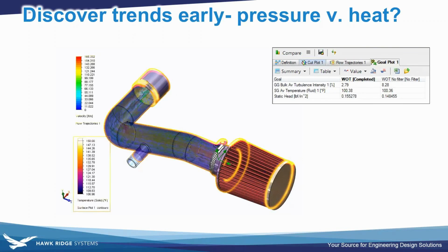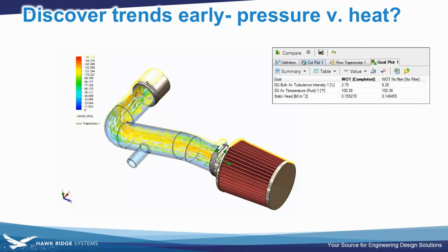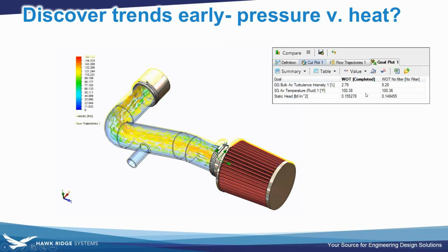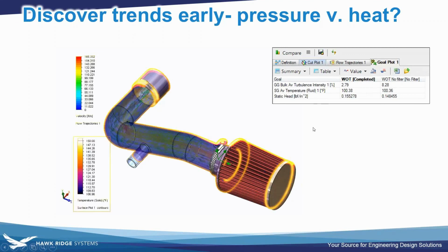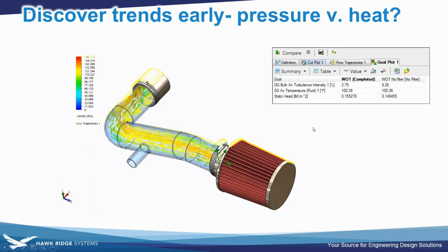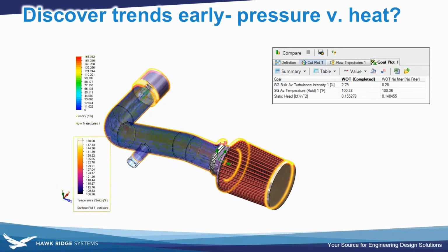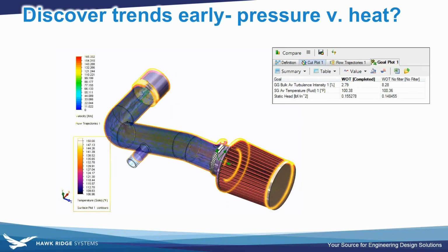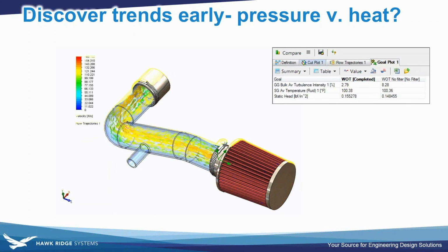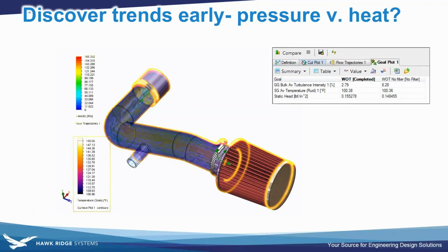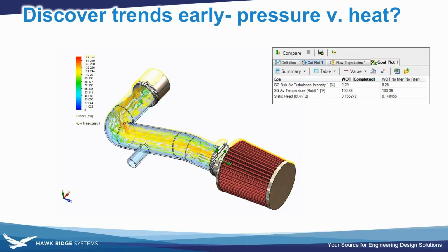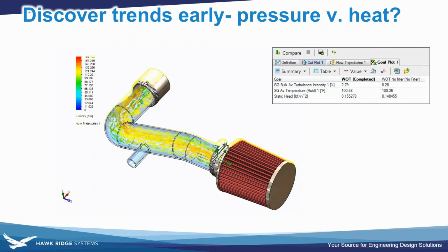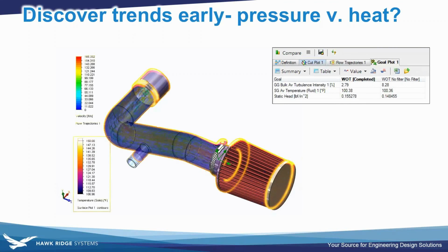And that temperature was only 100.3 or so degrees. We assumed that the air coming in was 100. So that means there was minimal temperature rise of the air going through the ram intake. So that means that this airflow was sort of high enough to negate any worries about heating from the engine bay or the external temperature coming in. And of course, if you wanted to explore other aspects of that, like putting in a heat shield or putting in insulation or maybe a different flow condition like a lower flow rate, you could examine all of those parameters.